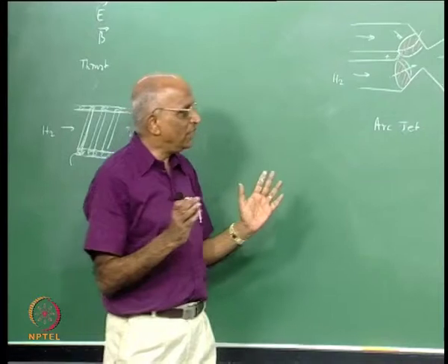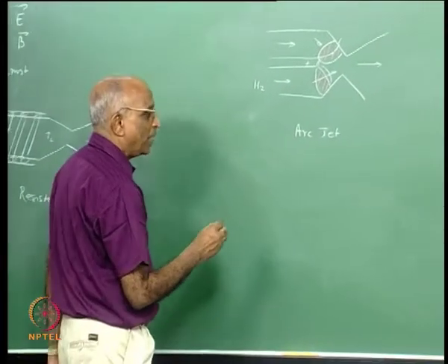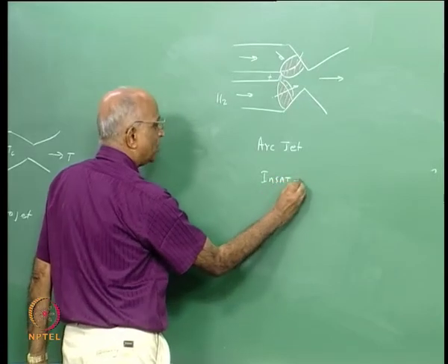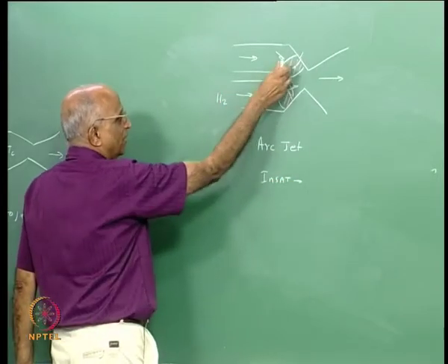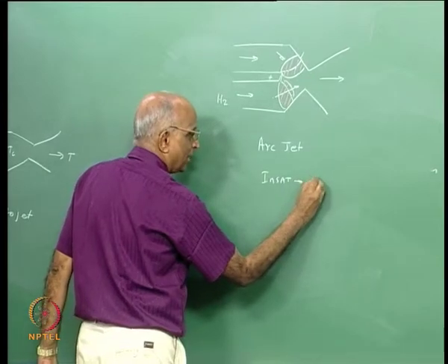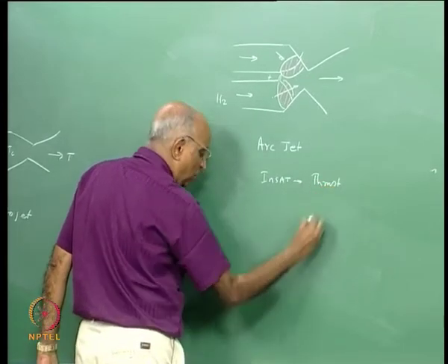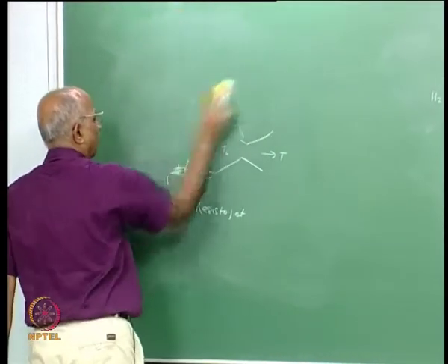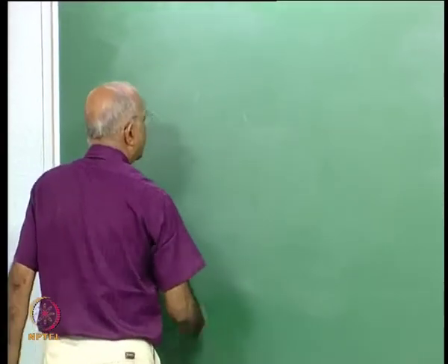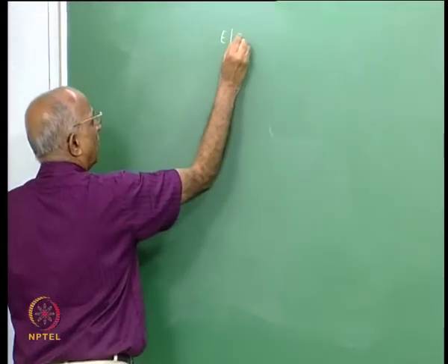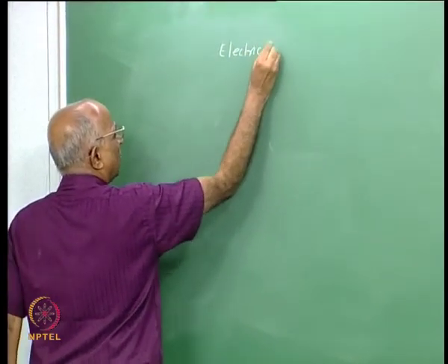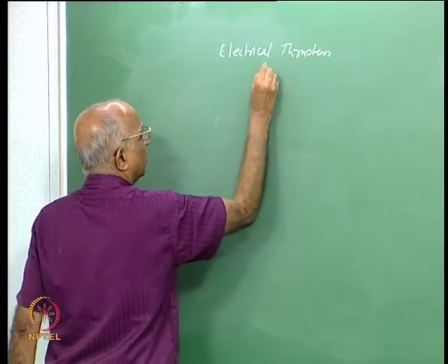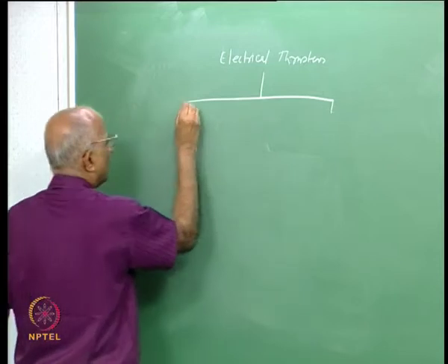In fact, when we made the first prototype or a discussion on Indian national satellite, INSAT satellite, we thought we will use ammonia as a gas with an arc and use it to generate thrust. Therefore, to conclude the discussions on electrical rockets, we can say electrical rockets are essentially, we could call them electrical thrusters, since they generally can be used only for low thrust.